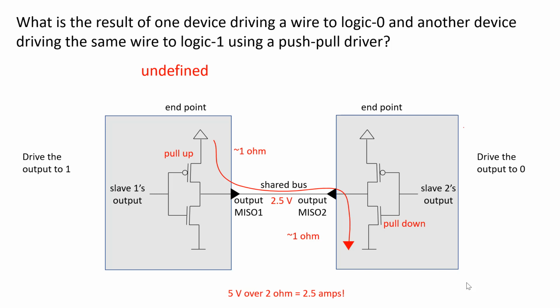Why are you emphasizing this so much? This is the reason why we use open drain drivers for I²C. But in SystemVerilog, it's also important because it's assumed by the language that all drivers are push-pull drivers. So when you write code in HDL, VHDL or Verilog, you have to avoid this double driving or contention or conflict problem because, like I said, it's a single-ended push-pull style of driver in general with SystemVerilog.